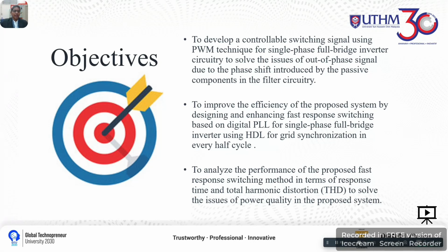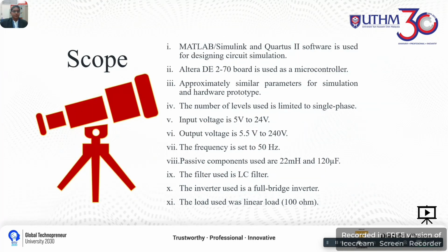And finally, to analyze the performance of the proposed fast response switching methods in terms of response time and also THD. The scope of the research is mainly focused on the software for the circuit development, which is MATLAB and Quartus II. The microcontroller used in this project was the Altera DE2-70 board, and the same parameters are used for simulation and also the hardware prototype.